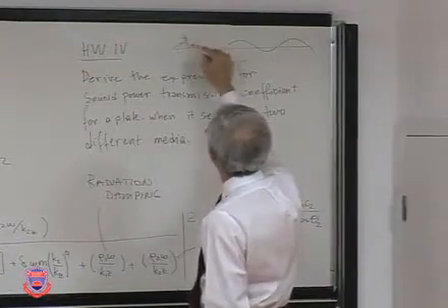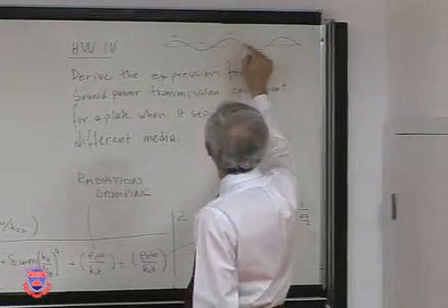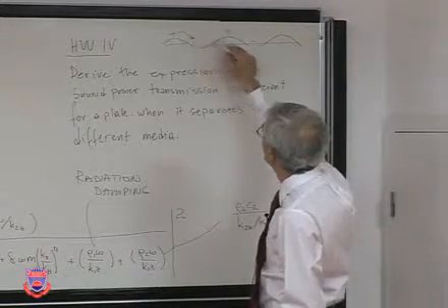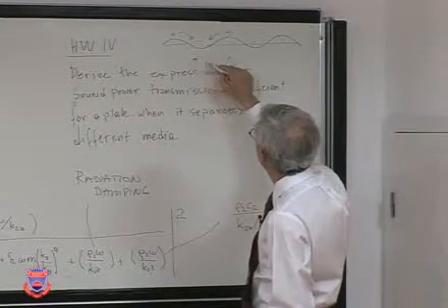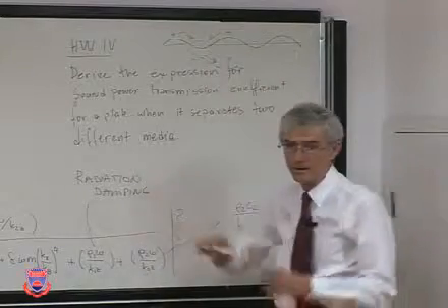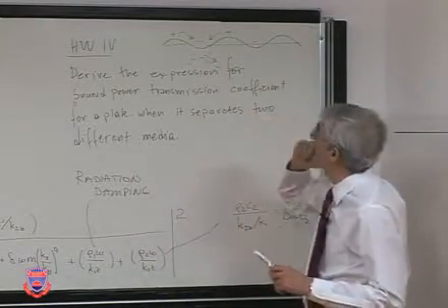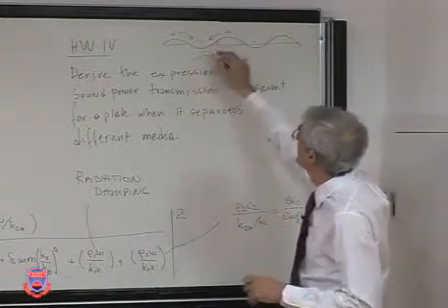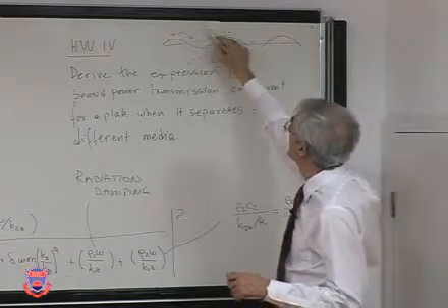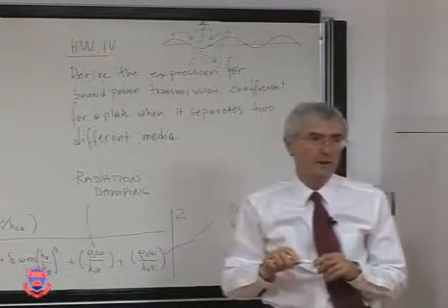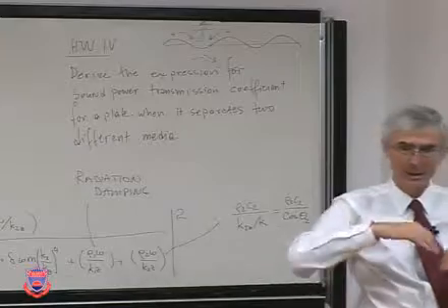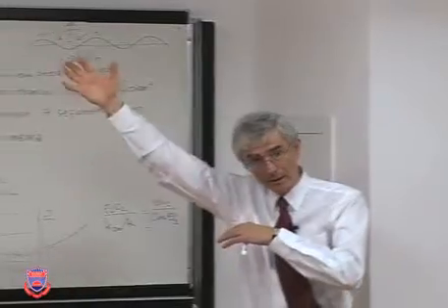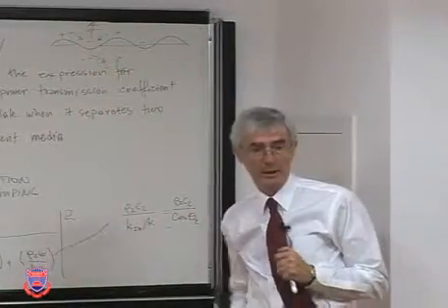In one cycle, it pushes the other up, down, as it moves up and down. So the fluid really just goes here. In the next cycle, it goes back. But if this were above that coincidence frequency, then it doesn't have time to go back and forth. It would just radiate outside. Physically, that's what happens. In one case, it's reactive, it just is around the structure. In the other case, the energy just radiates away.